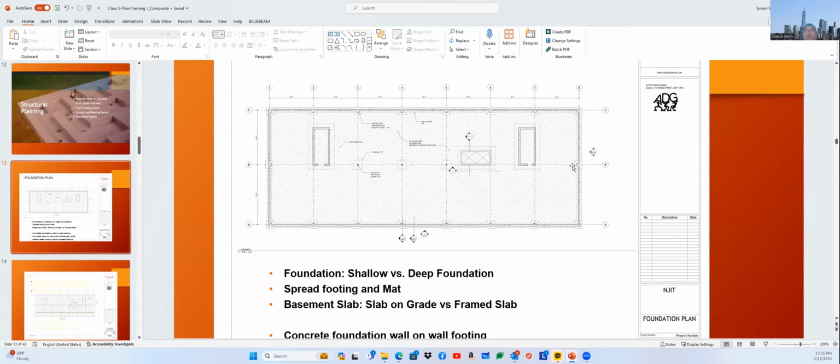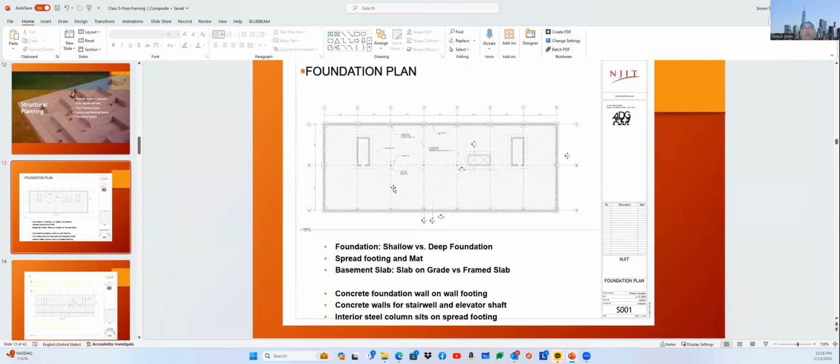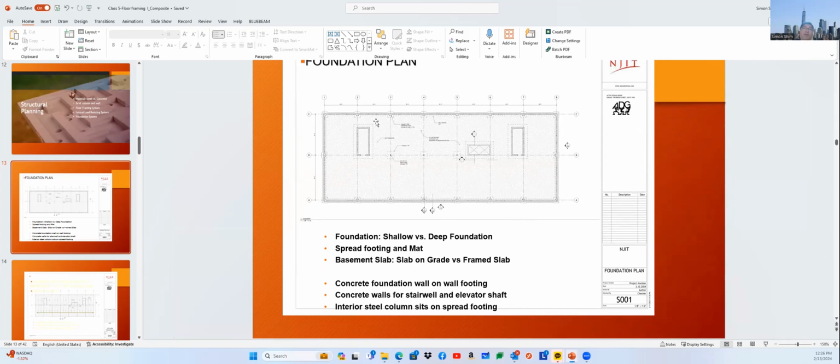So just looking at an overall system, even though this is relatively small, you'll see that we need a mat foundation, right, for your entire tower or partially the wall, right? And you need to handle individual column footing too, or in our case it is most likely an entire mat because of different levels of height and overall weight. So we need a slightly different approach, but the ideal concept is the same. We need to set our building on the foundation system, which could be shallow foundation. We normally, you guys learned, spread footing or mat, so that should be placed on the bottom of the structure.